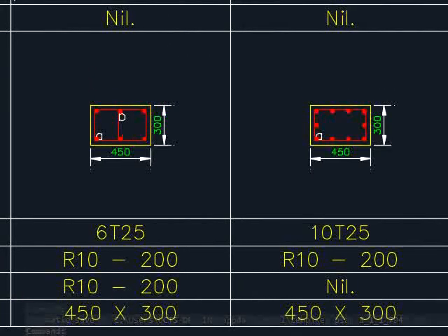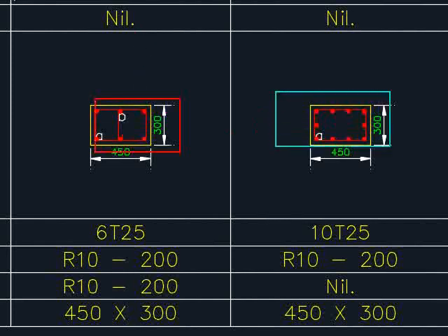For some critical columns, the amount of reinforcement bar may be extremely large. Where you have so many reinforcement bars, you should double check whether your calculations are correct or not. If you observe a very significant difference in the amount of reinforcement bar, even though the sizes of the sections are similar, you should go back and do proper checking again in case there is any mistake in your calculations.